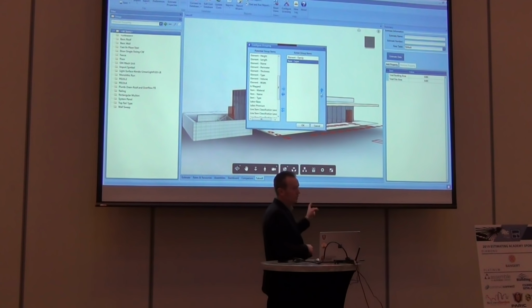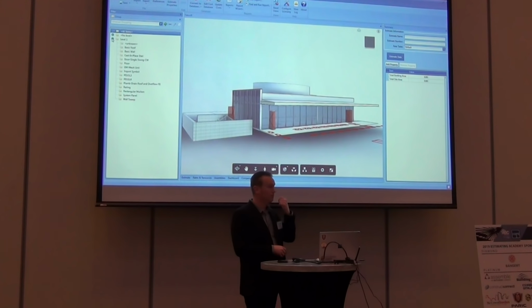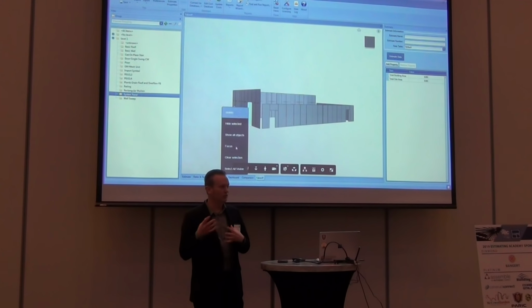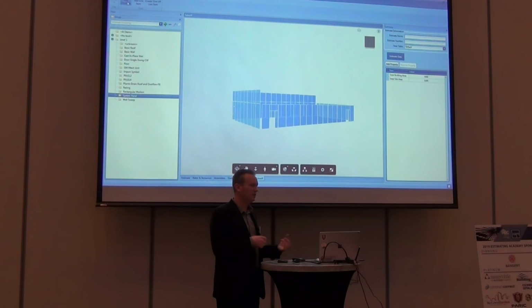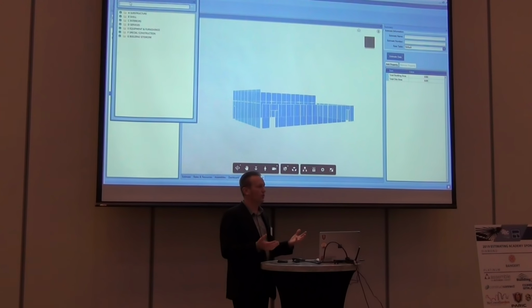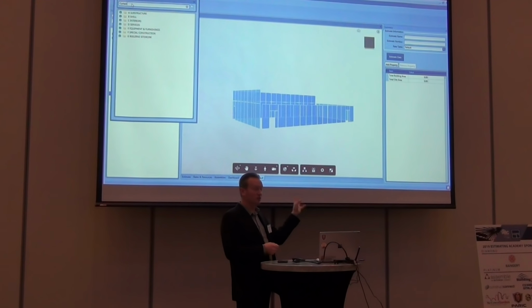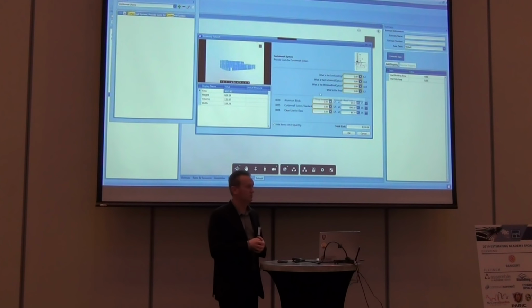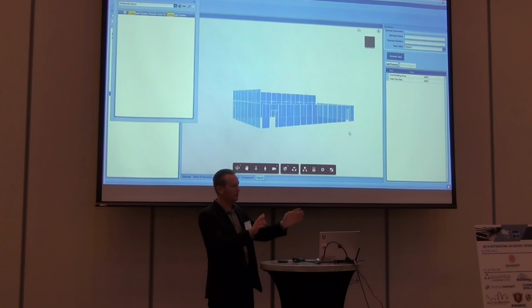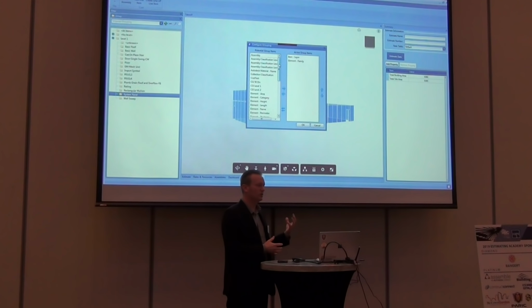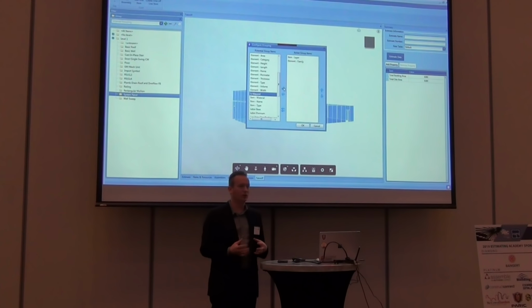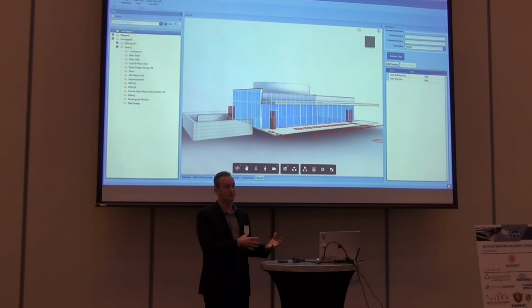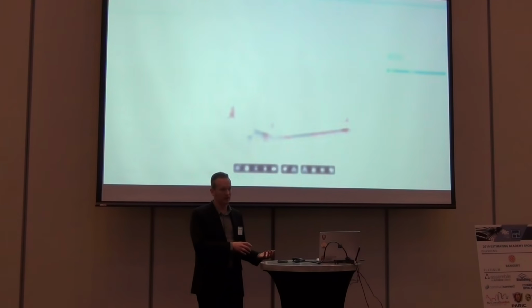This tool here is sorting and filtering that data. So if I know that the elements are best sorted and filtered using UniFormat, or CSI 16, or MasterFormat 48, or whatever, some of it's just custom properties. And we know that, hey, this was allocated to phase 2, and all we care about in this entire model are the phase 2 elements. It gives us a way to slice and dice this data without having to have the architect prep the model for us, or having the VDC team prep the model for us.